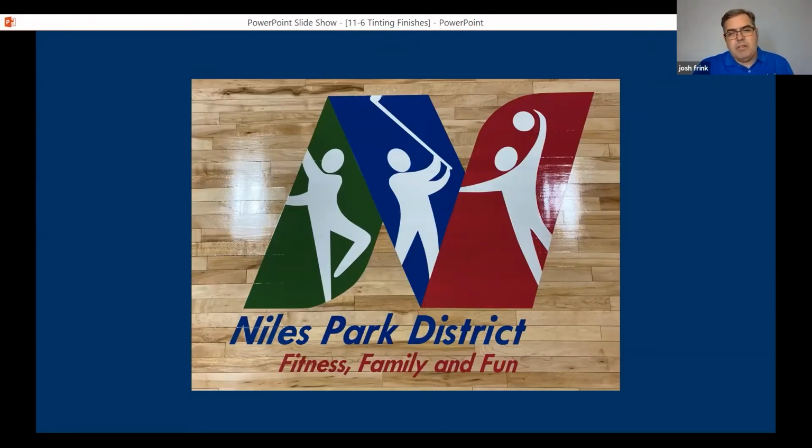All right, now let's do the math on this logo. So if you were going to put paint down to try and achieve this look, gym floor guys are usually looking at 1 color a day. They might have to do multiple coats, and then they can pull the mastic, put the mastic back on for the next color. So you count up how many colors are on this logo. The contractor's probably looking at about a week to accomplish something like this.